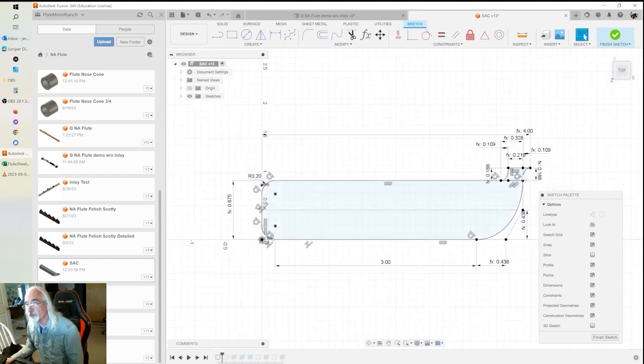These are control point splines with just one control point that I've made vertical and horizontal to create this nice arch that is set to the wall thickness that it needs to cut through, with a reverse one on the other side. Same thing. I've set this width, the sound hole length. I've set the top part of this, not counting the curve, but just the top part, to the sound hole length. And then I set each side of the arc to be 1/2 the sound hole length.